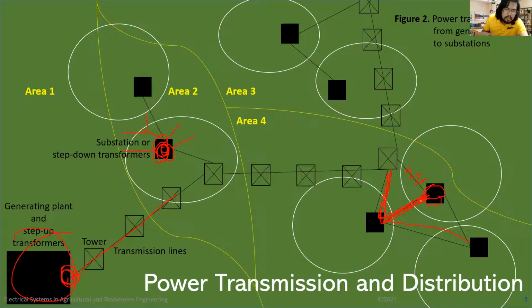So in reality, a power system will consist of power generators connected together via these transmission lines to form the grid of a power region. Now, should two systems with different AC properties be connected together, the high voltage direct current or HVDC transmission lines will be used, although merely to connect the power regions with different operating parameters.